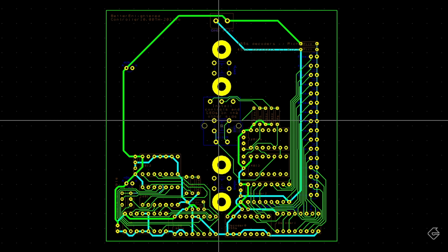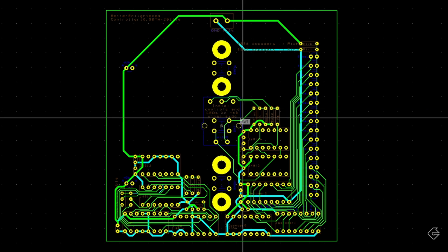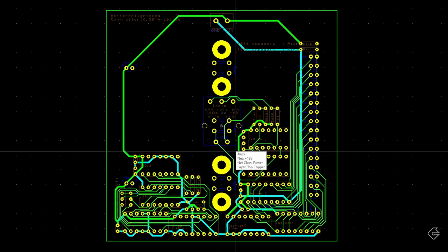Here's the 4 prongs for the reset button, and it's already wired in according to my design. Most PCB design software will throw an error at this point because I've basically put 2 components on top of one another. But for us, we can ignore the error because we know only one component is going to exist at any time. So now that we have all the buttons and the physical hardware and user interface stuff already in place, let's start putting in the electrical components.